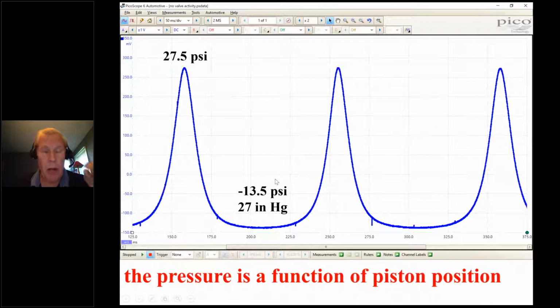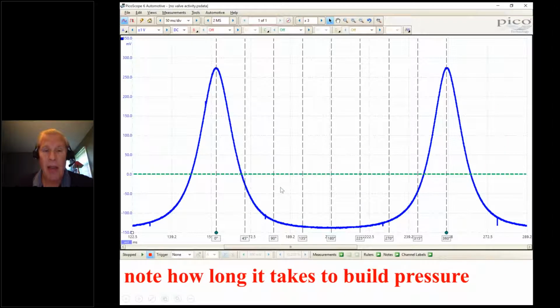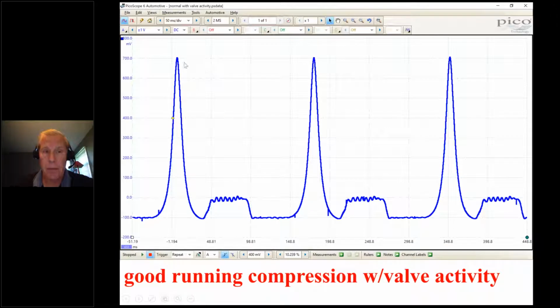And what I'd like you to think about is whatever pressure you start with, as the piston is being dragged down the cylinder, we have to relieve the pressure. The lower the pressure that you start with, you relieve it sooner. So if I relieve it here, I've got more stroke, the downward movement of the piston, to create a low pressure area in the cylinder. If I start with higher pressures, more of the stroke is used to relieve the pressure.